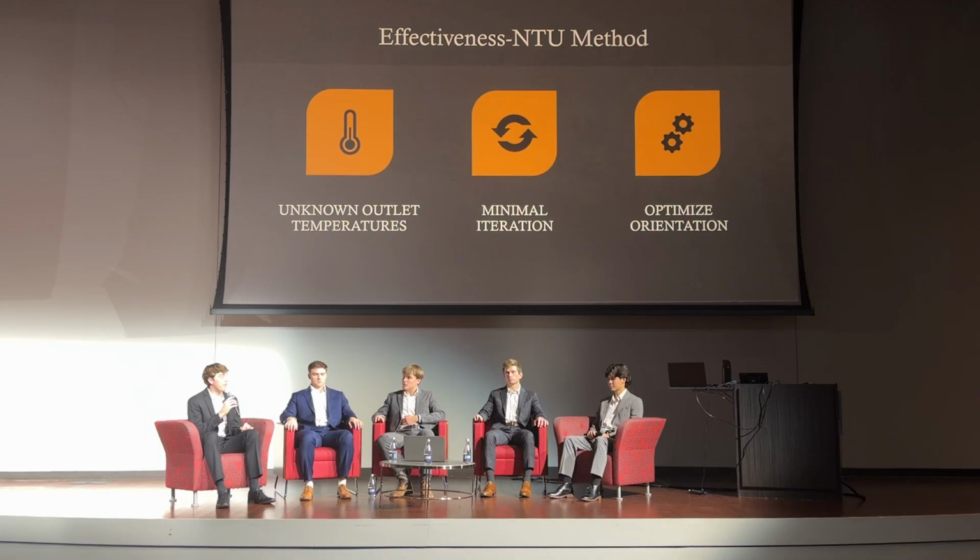So to start off, the effectiveness NTU method is a huge part of any heat exchanger analysis. What makes this so crucial is that you can do all these calculations of effectiveness based strictly off of the inlet temperature. And so it limits some of those iterations that you would normally have to do with the log mean temperature difference and other calculation methods. You get rid of some of those iterations and can get straight to your efficiency and effectiveness, which then can let you optimize doing different correlations to figure out if you want cross flow, parallel flow, counter flow, and how you want to set up your heat exchanger.